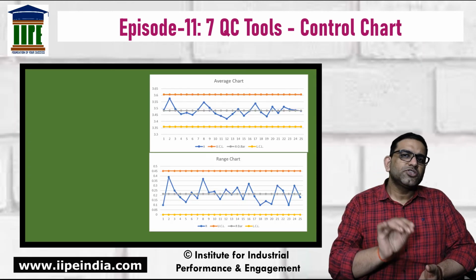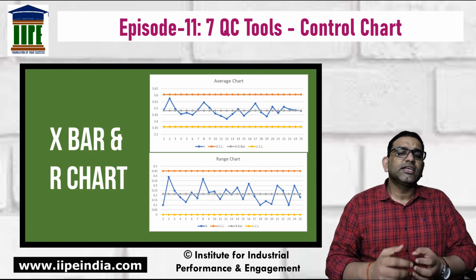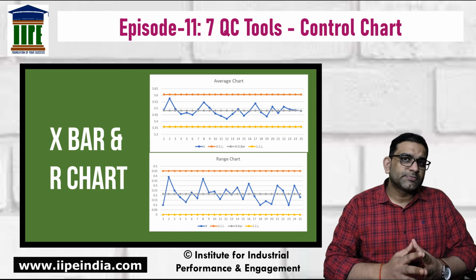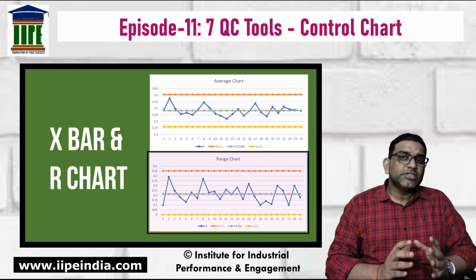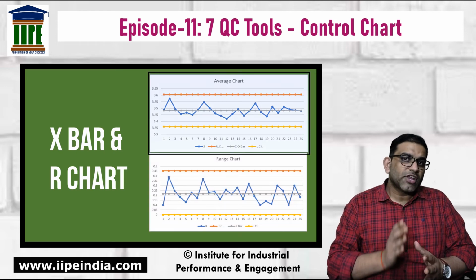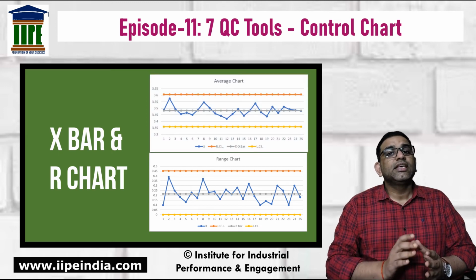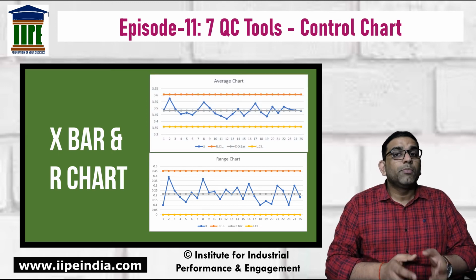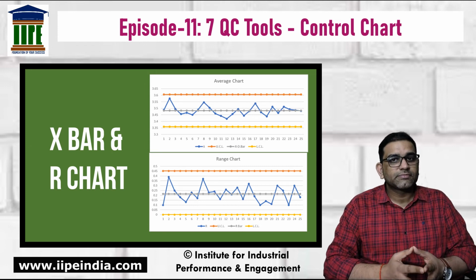As you have seen the process of creating X bar R control chart on Excel, let us quickly discuss its interpretation. Always start with the range chart. If all the points are within the control limits, then go for the average chart. If in the average chart also all the points are within the limits, then this means things are settled as of now, but one should also look for the validation of the control limits.